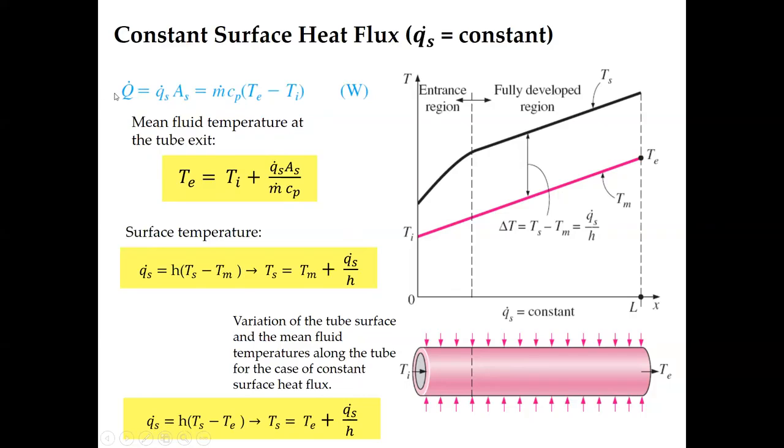You want to know how much heat you put in the system. So basically you calculate exit minus inlet, multiplied by the heat capacity and the m dot. Next you can rearrange this equation, because this is equal to the heat flux from the surface multiplied by the surface area, and you get the big Q. So big Q is given from the temperature difference, and then it translates into the Q on the surface.